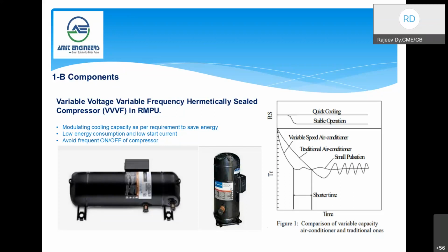Yes, sir. Say, for example, the cooling capacity of the unit is 8 TR, considering the maximum ambient of 50 degrees. In the worst case, at 50 degree ambient, the internal heat load will be higher. Considering that, we are designing this system, whereas it will not be the condition all the time. That is the worst case, since for railways it is a moving application. The machine is designed for the worst case. Whenever empty coaches come, maybe in summer, the internal temperature will be higher.